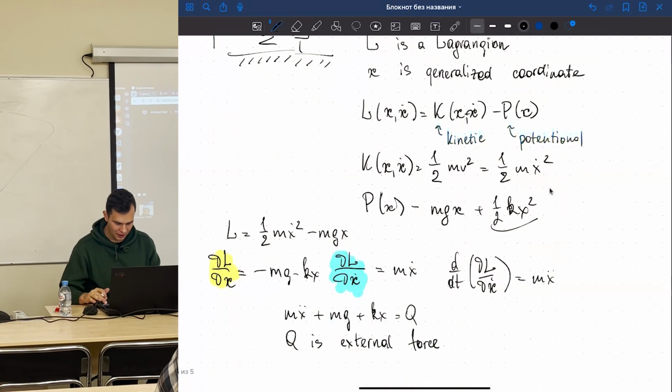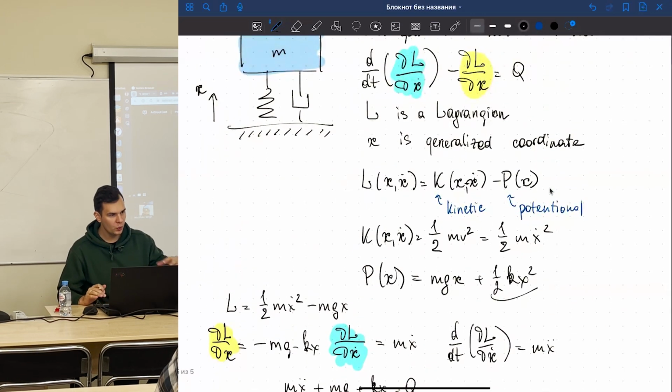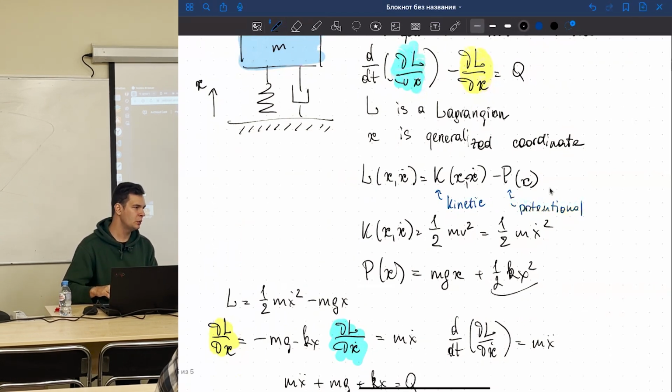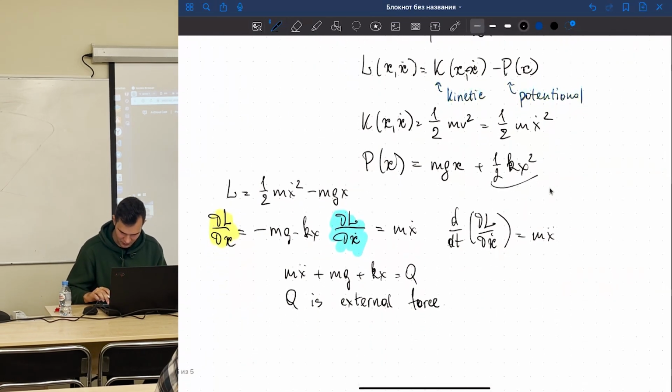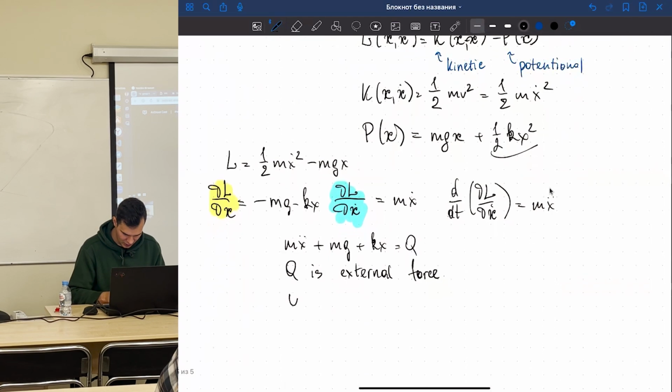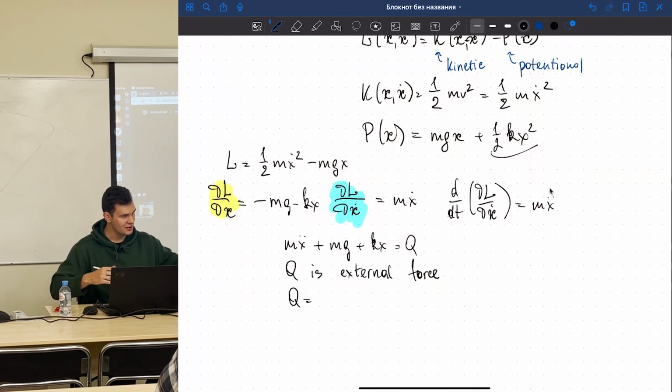You cannot destroy energy. You can irreversibly transfer it to heat, a temperature rise, because the amount of energy is constant. And here Q will be an external part that sucks energy, and here Q will be the force of the damper. So what will it be? B x dot, yes, you are correct. So it will be Q, and minus because it sucks energy.